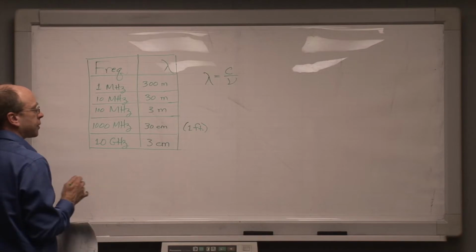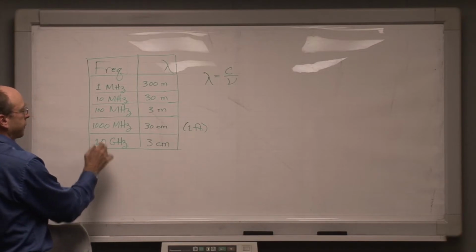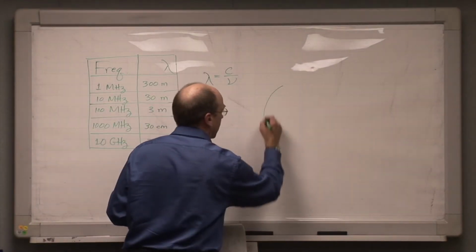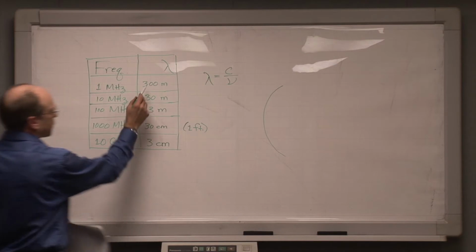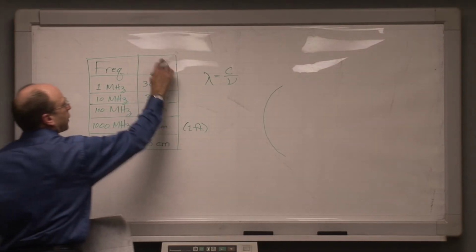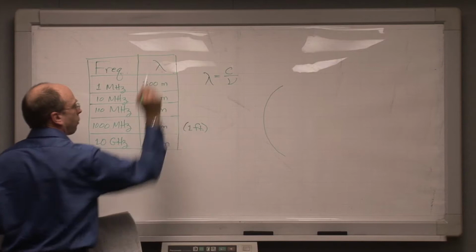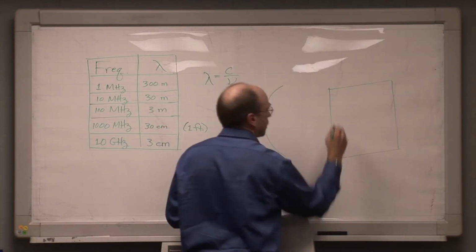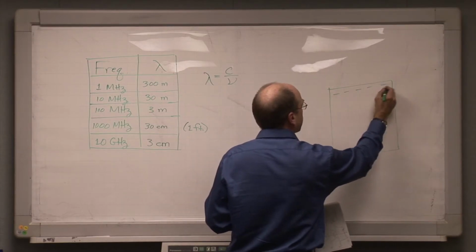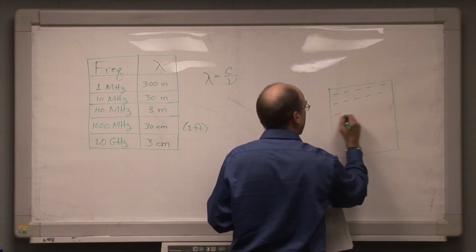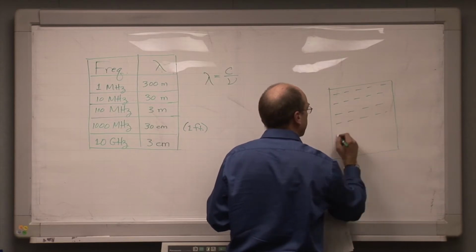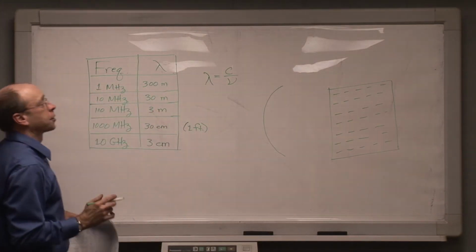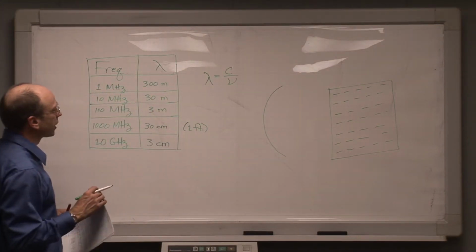And based on the description that I just gave, if we want to direct this energy strongly in space, we're either going to need to build a parabolic reflector at any given frequency, which is substantially larger than this wavelength lambda, or equivalently, we may want to build some kind of a phased array. But even if we want to do that, the phased array size overall is going to have to be, and I'm drawing a phased array with elements on the face, still rather large compared to the wavelength of the radiation that we're working with.